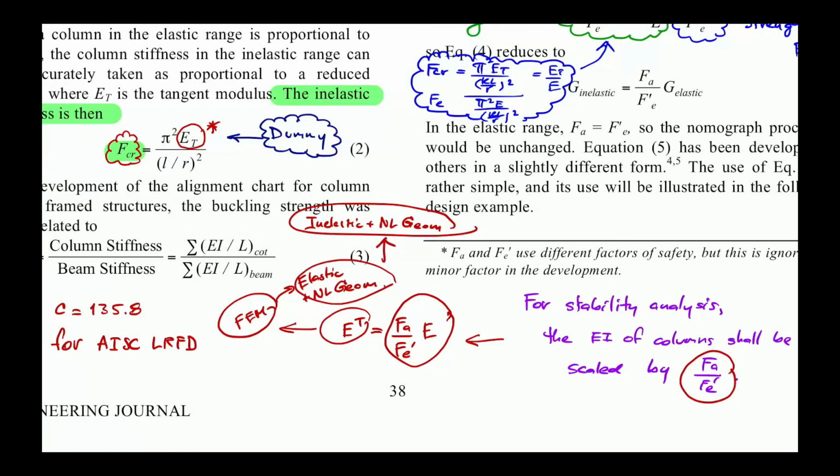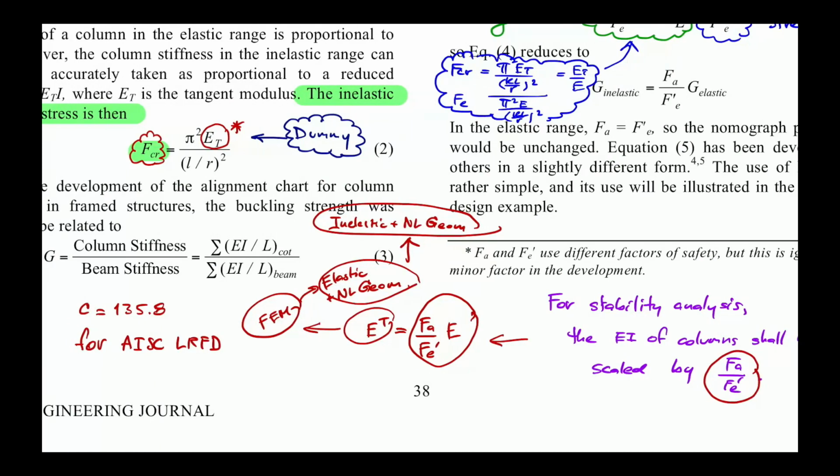This is more work, right? If you want to do inelastic analysis, your frame structure has to be discretized, and you have to put in rotational springs to cap the moment capacity, maybe also in the middle to make sure that you enable the column buckling properly.